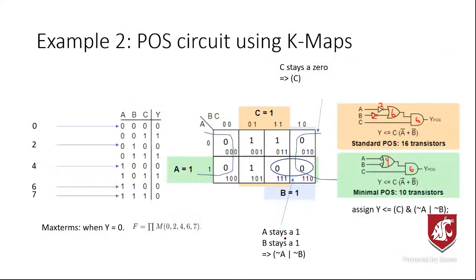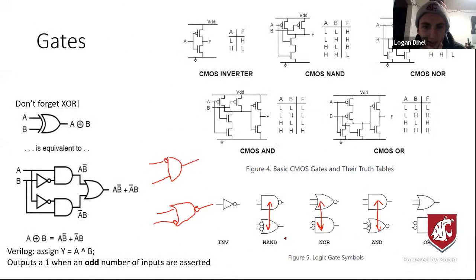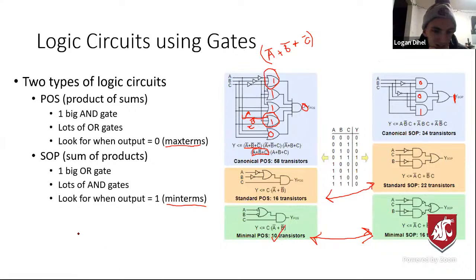So going back, Logan did mention it last time in our review that if you have 2 little dots next to each other, they do cancel out. Oh, yes, that's a good point. Here's an example right here. See these 2 dots? That's equivalent to here with no dots. Exact same thing, because a not inverts it one time, and the other one inverts it back. So if you see 2 bubbles, you can just eliminate both of them at the same time. That's a good point.